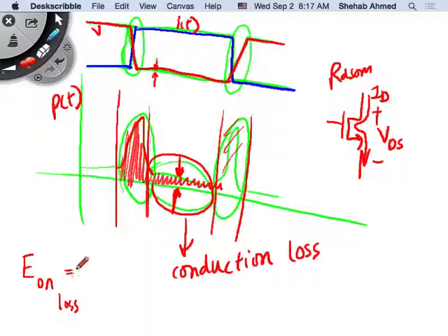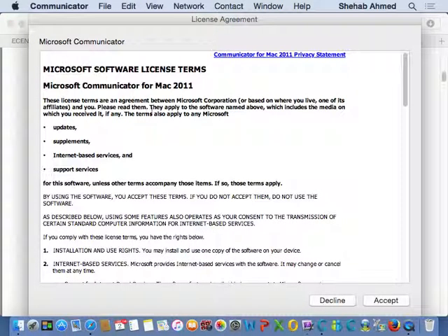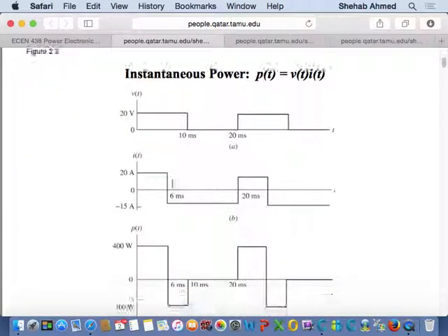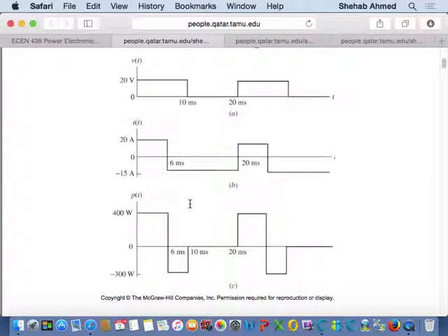Okay. So how would you do that? We said the area under the curve is basically the integration of the curve, right? So the energy is the integration of instantaneous power, right? So you will be given such waveforms, for example, and be able to calculate. Simple waveforms like the one we saw here are an example, or more realistic waveforms like switching loss waveforms are the same.